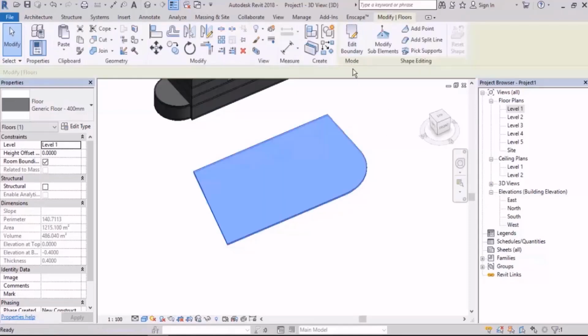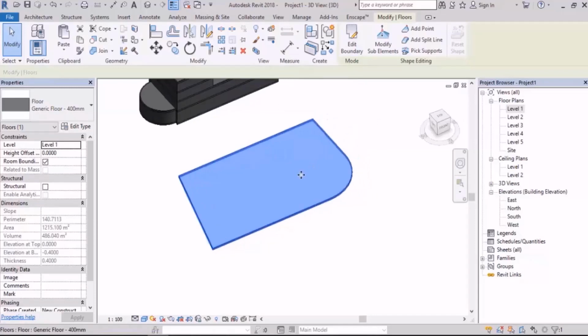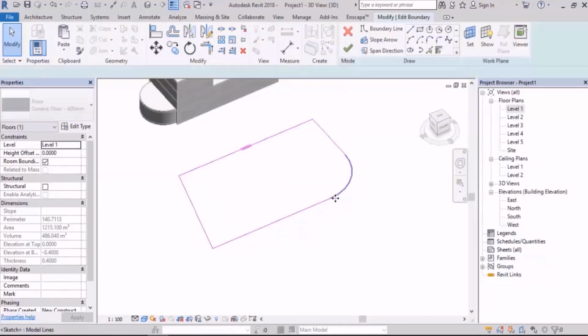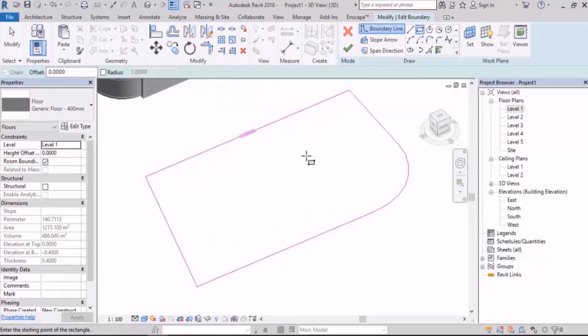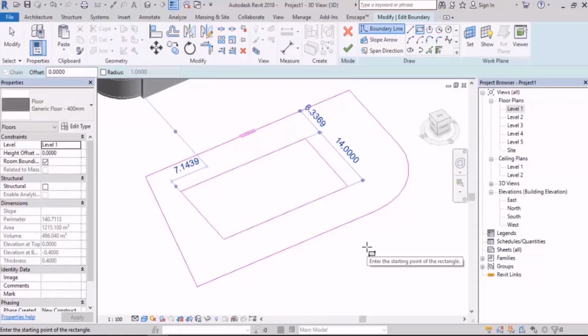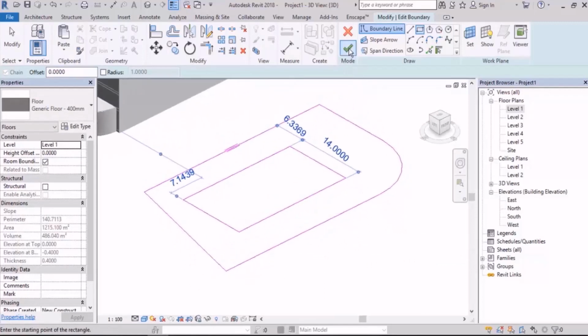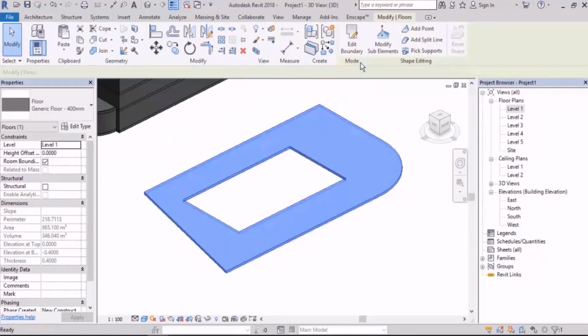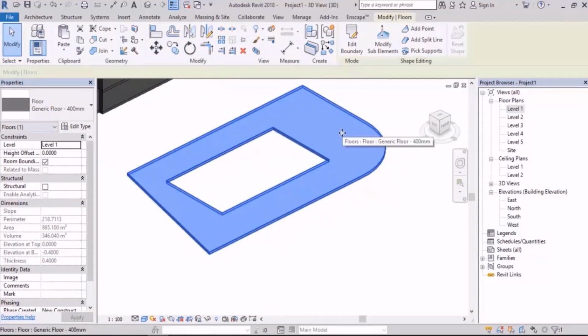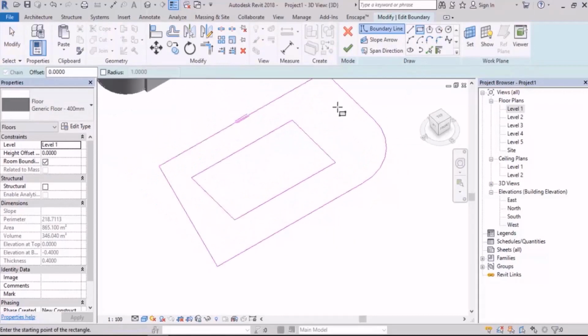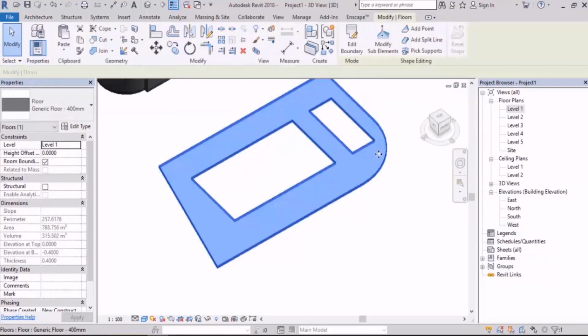Alright, now always remember something. In Revit, anytime you see an edit appears after selecting an object, instead you can double click on that object. Double click on this floor, for example, if you want to edit it. It's the same as clicking on edit boundary. Now, one question. If I draw another shape into this, what do you think happens? You might have guessed right. That's right, it's empty. So, if we draw another shape into our floors, a hole is created in it.